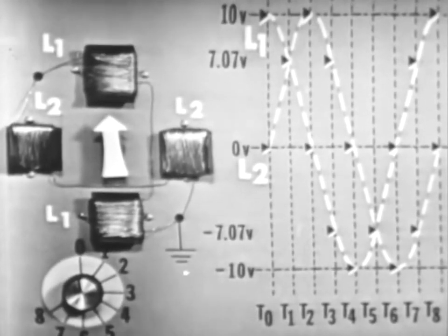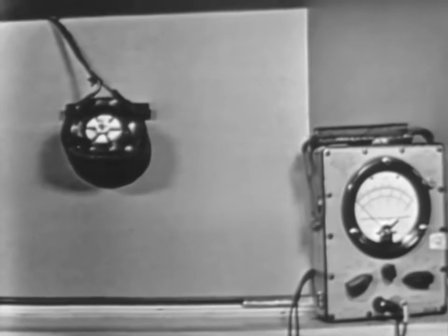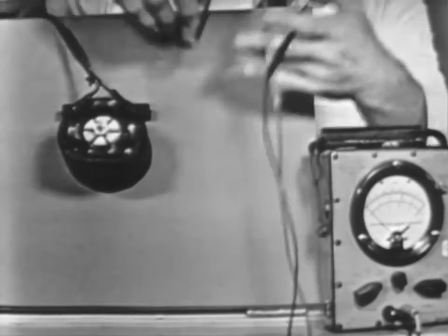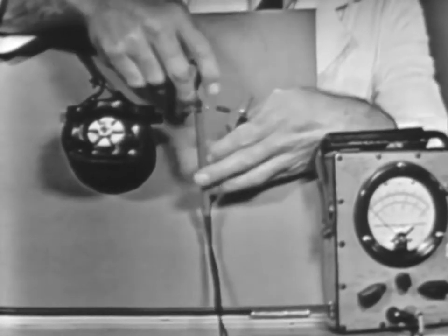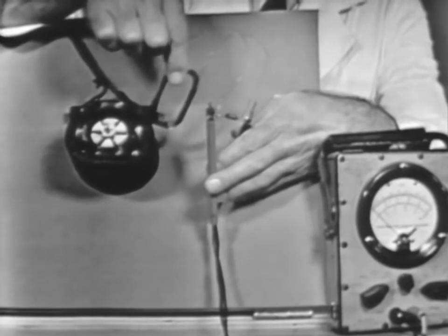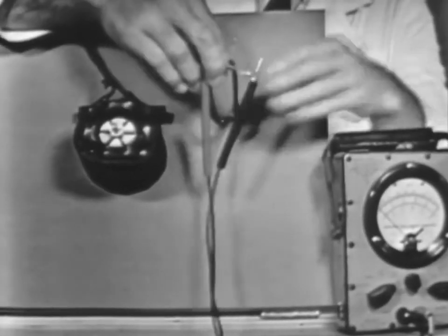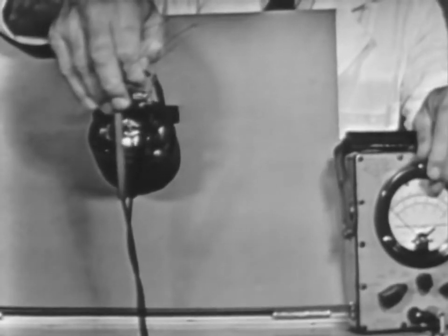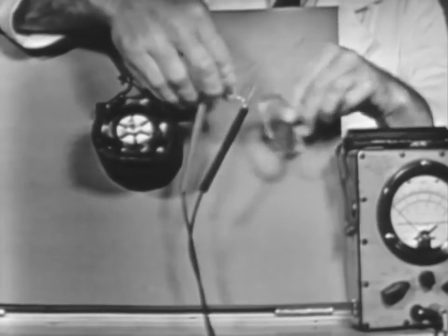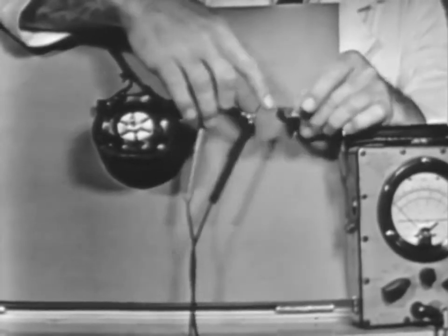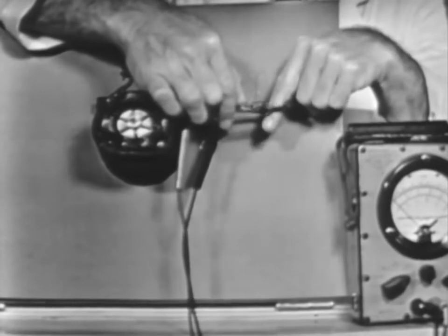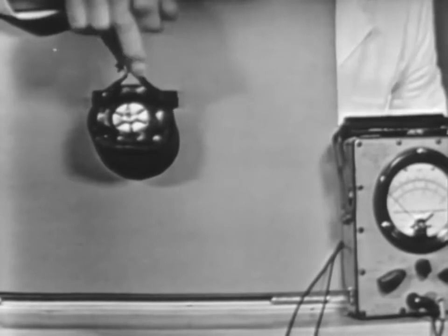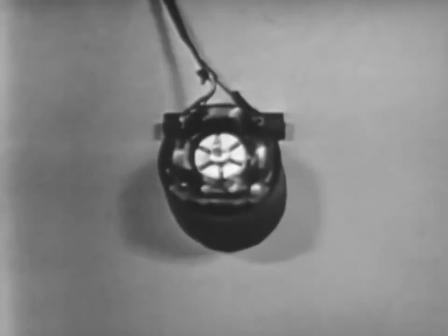Right. Now, I'll take item 4. All right. Help us out. All right, item 4, the rotor acts like a magnet. Well, it actually becomes an electromagnet and follows a rotating magnetic field because of induction. Okay, and we proved that with this little loop of wire, the resistor and the PSM6. We put the loop in the field windings, and the PSM6 showed us that we did have a voltage induced into the loop, causing current to flow. Once we had current flow, we know that the loop had to become magnetized and exhibit a north and a south pole. And once it is magnetized, it has got to follow the rotating magnetic field.